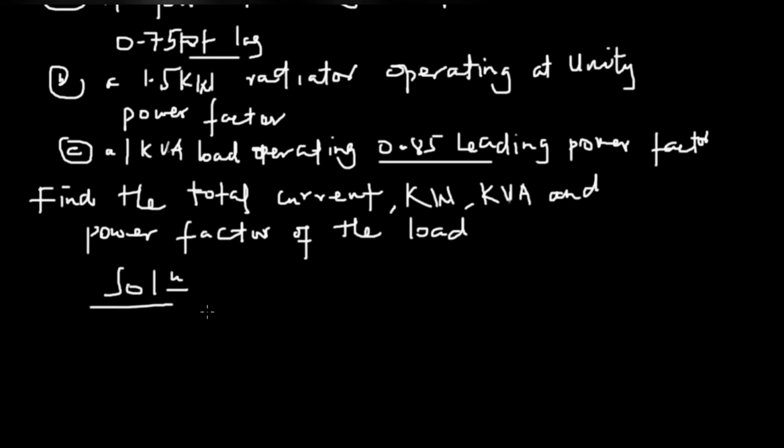So we have to find the total current, kW, kVA, and power factor of the load. Let's dive right into this. Now let's draw a table. We have S, that's kVA, then we have cos theta, and then we have active power, which is in kW.